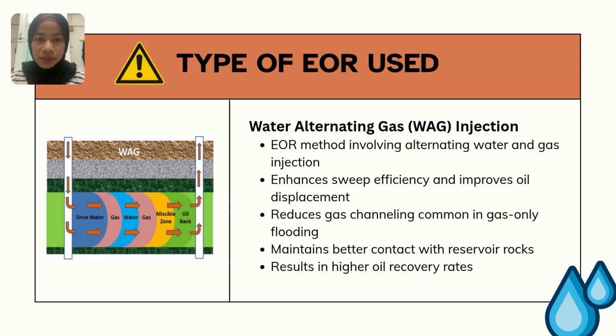This alternating process also improves contact between the injected fluid and the reservoir rocks, allowing more oil to be mobilized and recovered. So overall, WAG injection enhances recovery while managing gas breakthrough more effectively than traditional methods.